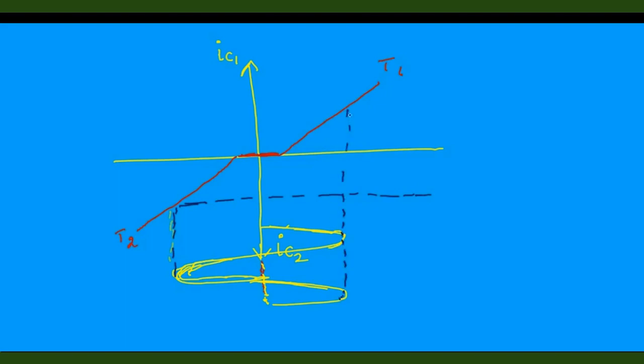Now here there is a problem, because for some part there is no collector current. Therefore, a distortion comes in the output signal. So this is the distortion here. Some part of the signal is missed in the output. This happens for the exact class B operation, and this is called crossover distortion. It is always present in the exact class B operation.